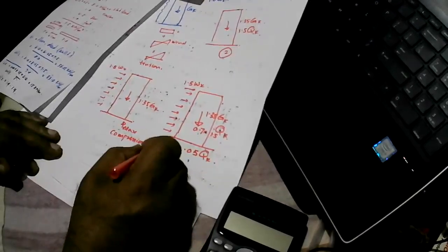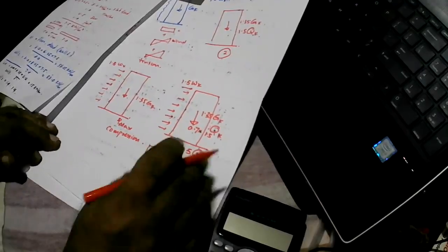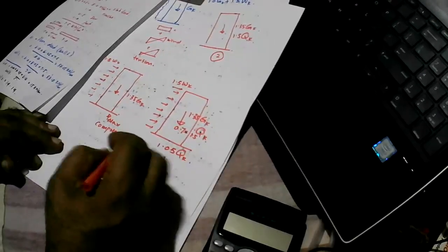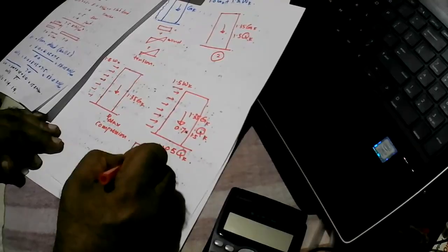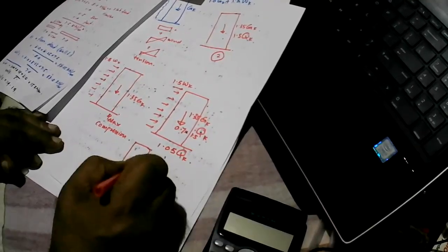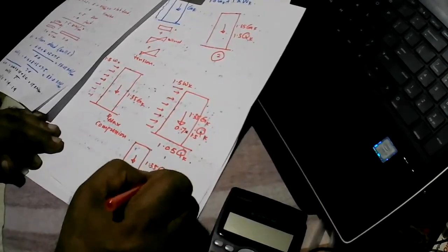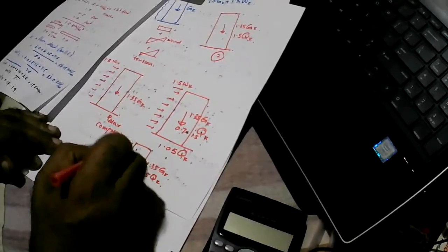Then the next one is the dead and imposed will become permanent and primary, and the other one becomes others. So you get 1.35 Gk. Here you get 1.5 times Qk. What happens to the wind?